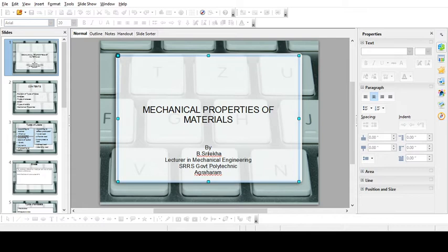Next comes shear strain. So shear strain is a measure of the rotation of the planes perpendicular to the applied shear load. As we have already discussed, only a face of the body of the member will be distorted due to the shear load. So for this we take certain assumptions and derive the formula. It is simply the shear deflection per unit length of the member.